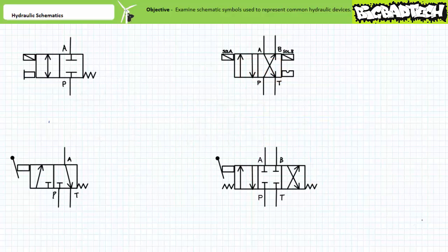Directional control valves are valves that stop, start, or change direction of fluid flow. Directional control valves have a number of identifying characteristics. Positions are particular functions performed by a directional control valve. Ports or ways are the number of ins or outs to the directional control valve. The actuation method is the means the valve is shifted from position to position.